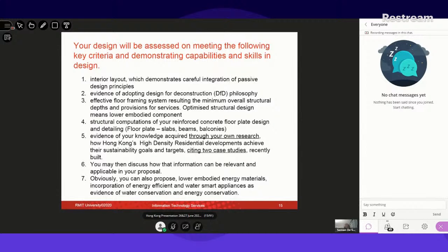to convert it to something else, or even the person who is residing there would like to retrofit or change the interior layout system, it can be demolished, it can be removed easily without generating a lot of construction waste. And then can you deconstruct it and reuse it inside? So that is the idea we are looking for, where your internal wall system can be removed, disassembled, rather than sort of permanently there and then demolished. So disassemble and demolish are two different things, okay?